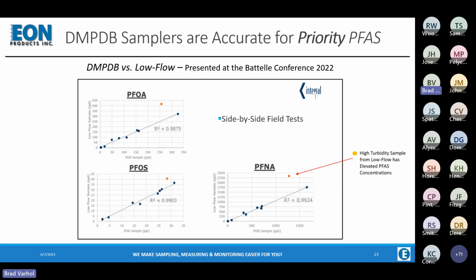And of course, we know from laboratory data and other information that PFAS tends to attach itself to colloids. And if we have unfiltered samples, we're going to artificially raise the concentration of the PFAS in the sample. The other interesting thing is that throughout the study, this same effect exhibited itself, and it caused the reporting limits to actually increase.